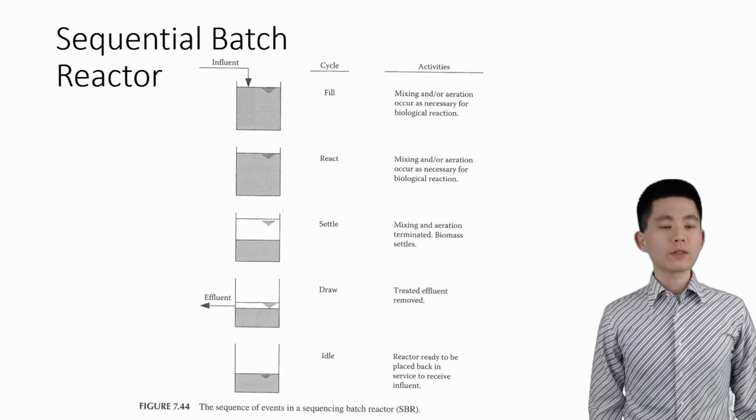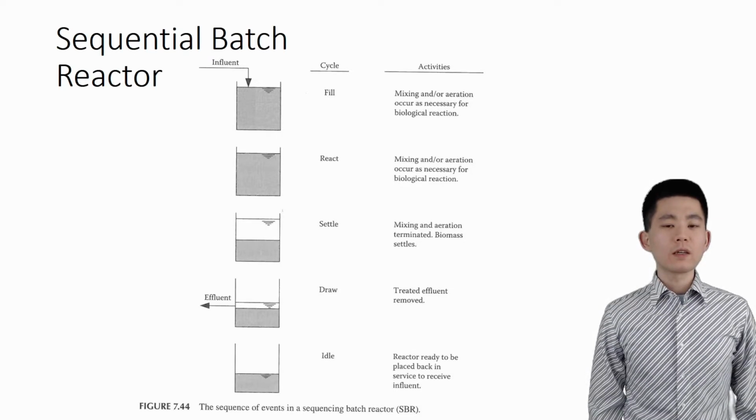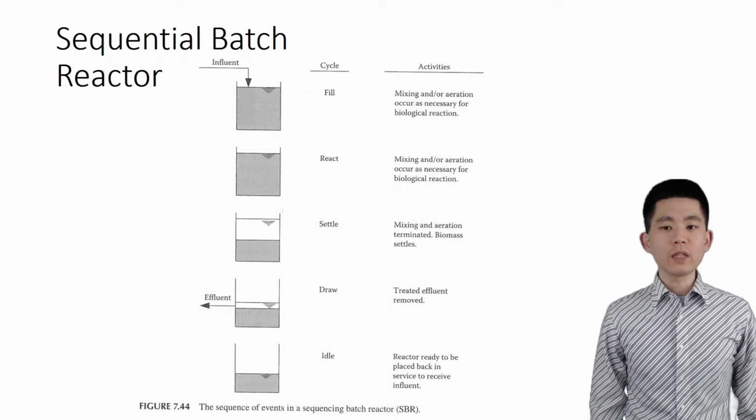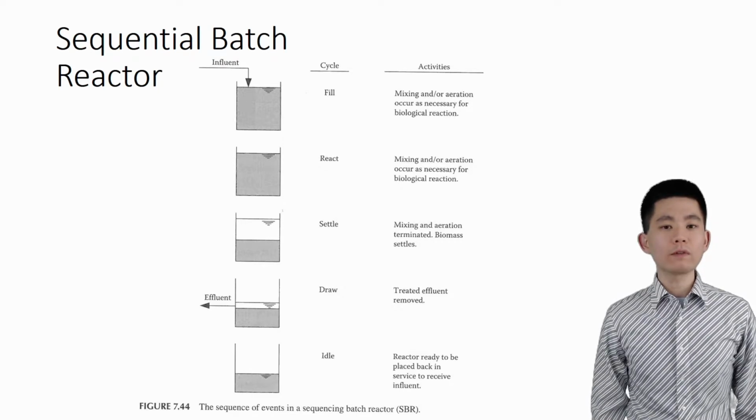To mimic the mixed liquor recirculation, a portion of nitrate-rich supernatant after the aerobic reaction is left in the reactor to mix with the influent with abundant organics for the next batch. This is equivalent to recirculation of mixed liquor.